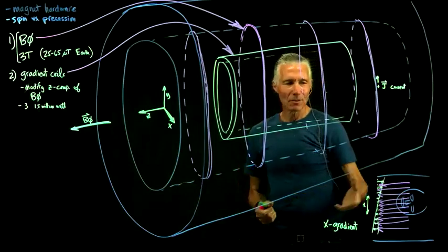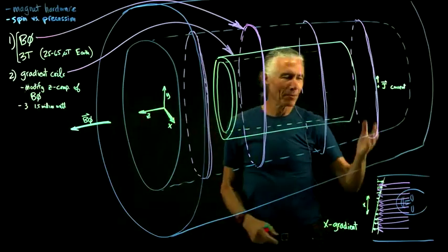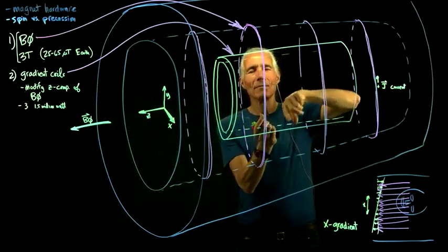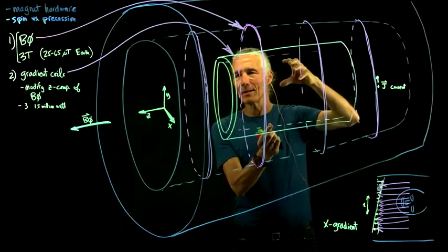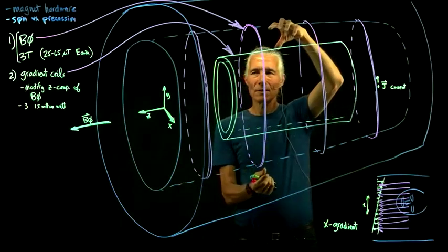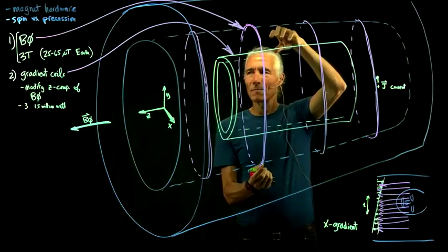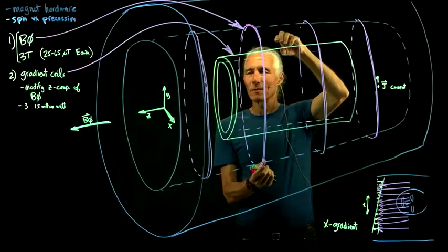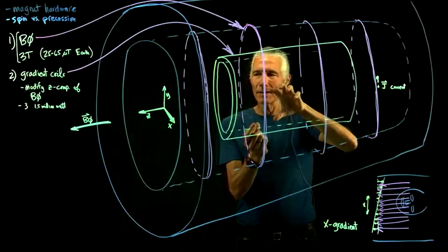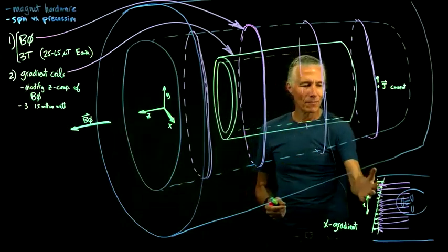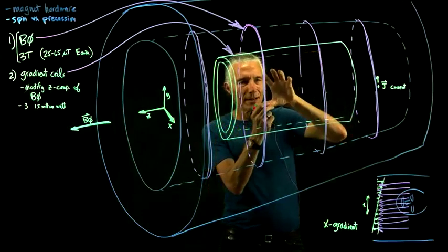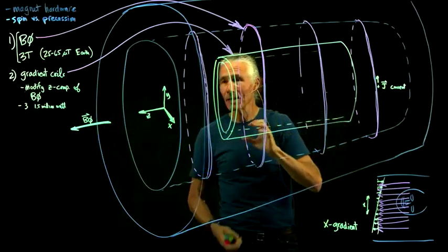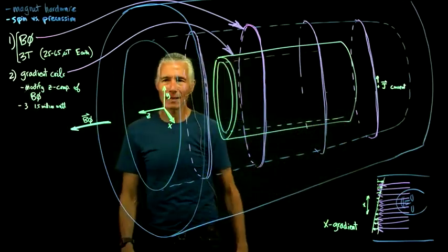But as soon as you power up the million watt amplifiers, the gradient coils make a magnetic field. That magnetic field will interact with the B0 field, since it's in a different direction, and it will try to move the gradient coil a little bit. Then when you flip it the other way, it'll try to move it the other way. So this giant 2-ton gradient coil is moving, and that's what the noise coming out of the magnet actually is.